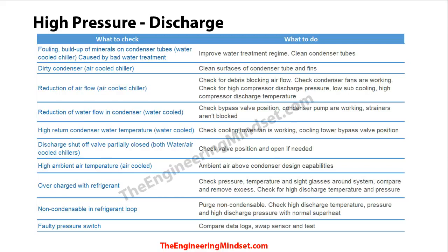And if you need to check this and you don't know what the values are of what the flow rate should be, then you want to look at the commissioning data, which was when the chillers were installed. They would have been commissioned, or they should have been commissioned, and through there it will tell you what the flow rate of water should be into the chiller through certain points through the pipework.